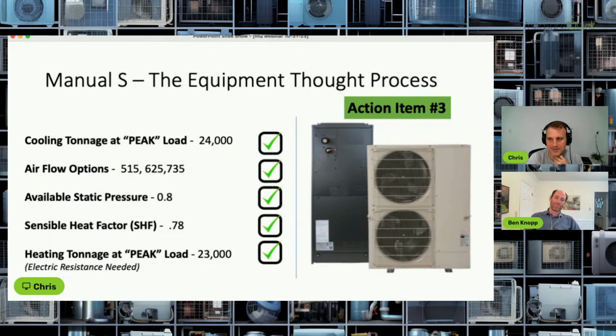So we had to make a tough decision here, right? So we went with the aggressive tonnage of air conditioner because we want the longest run times we could get in the summertime to deliver comfort. So that was the big decision to go with the 2 ton.